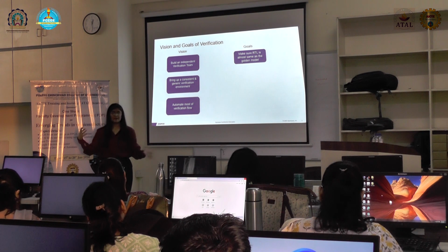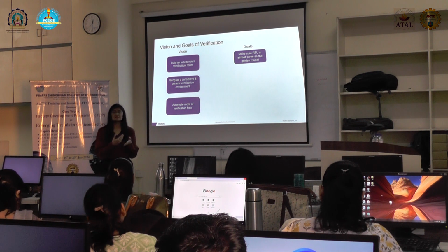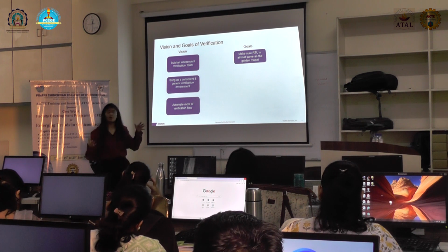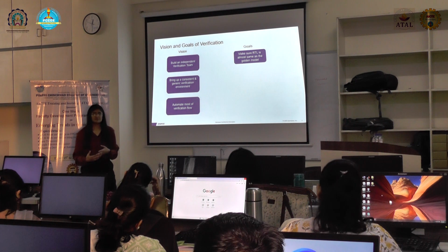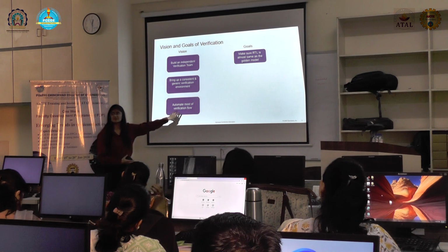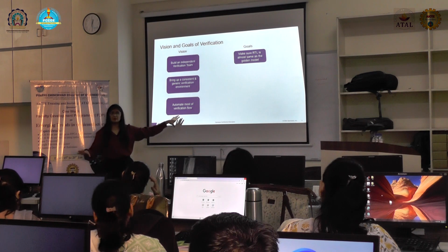Perl script could be there, Python script could be there. We can filter out errors from all those folders and create one final report which will just focus on errors. So we can just focus on debugging those errors instead of doing manual work going through all the folders and files. So all those things, cleanup, collection of errors, report generation, tools needing to be enabled for specific features, come into the part of automation, and that is a very important part to have a smooth tapeout for any product.